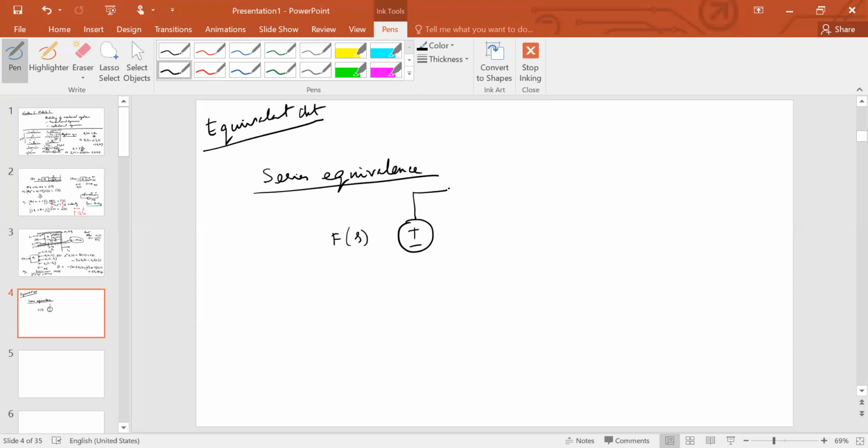Remembering that, we leave this part empty for the time being. So clearly there will be two loops. In the first loop, there will be a current, which is going to be given by x1s. And we draw this capacitance. Since the mass is 1, the reciprocal is also 1, so this will be a 1 farad capacitance. And then we have a 3 ohm resistor. So this will actually give you 3s plus 1. What to put here?